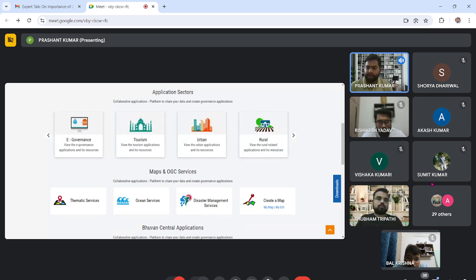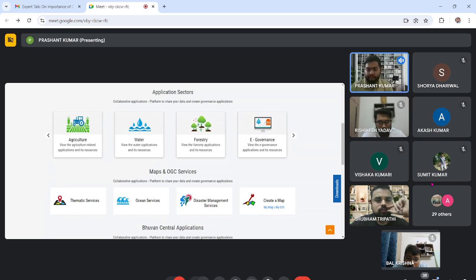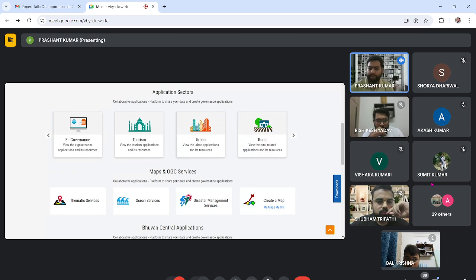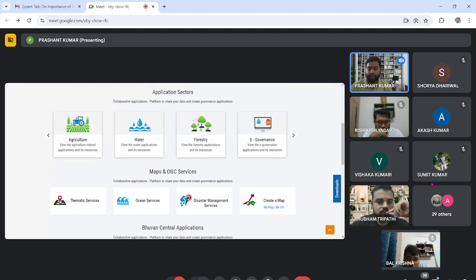Now you see, as my project is located in Shimla, I can get the complete data: where the alignment is going in the structural origin, where there are dissected hills and valleys, where I'll be having fluvial regions, where our water body is located. So this complete data is there. Not just that, it has land use, land cover data also, which I have already shown for that alignment of J and K. Whatever there is, built up, urban, rural, whatever it is, we can use this data and implement it in finalizing our alignment, finalizing our solutions.